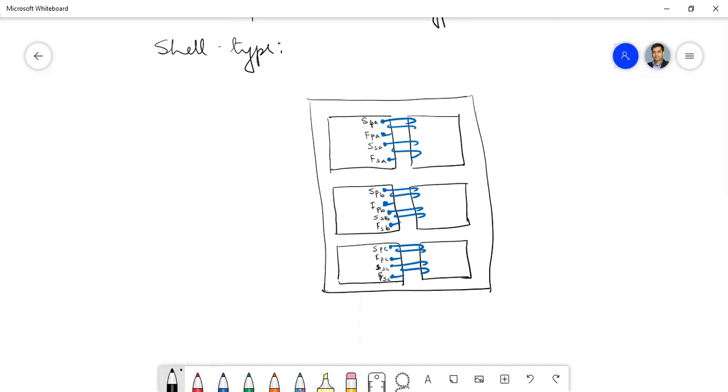But only 3 limbs out of these 9 limbs are used for the coils, and the rest of the limbs are there for flowing the flux. For A phase, the flux will flow like this. So these are the flux lines for A phase.